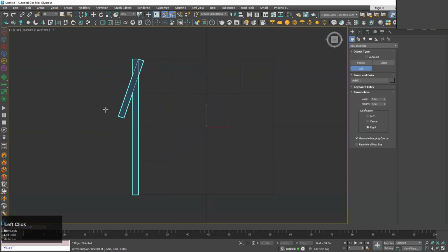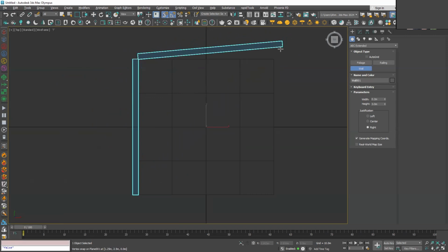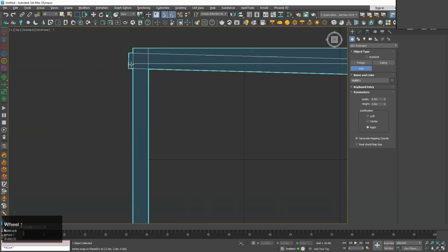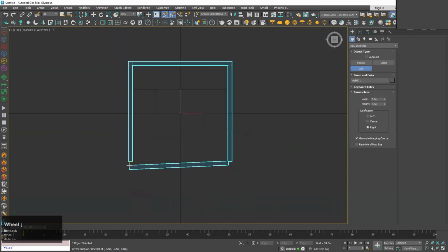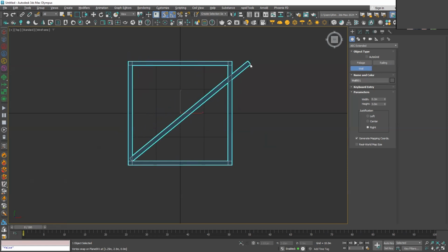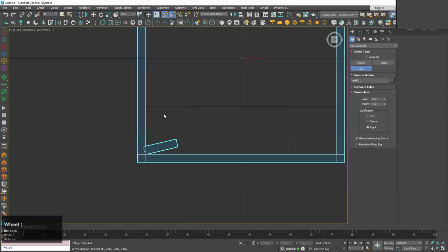point, and after the second point you can see we still have our wall activated. So this means if I go to the third point and click on it, you can see now that this gap is filled automatically. And then for the last point, just click and weld points and say yes, and this is going to create your walls and weld all the points or fill up all the joints we have over here.